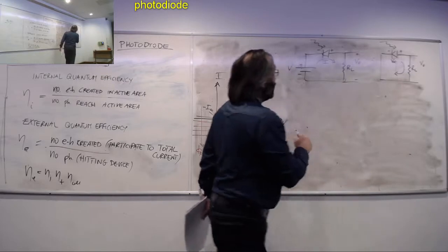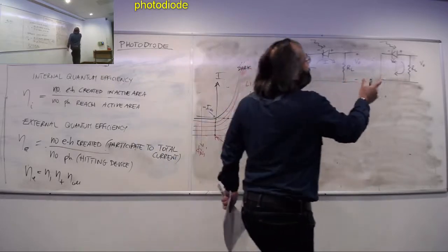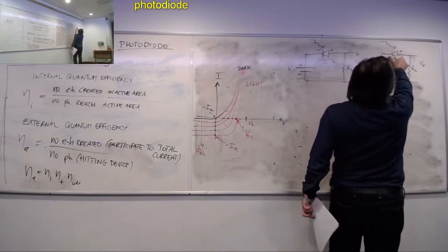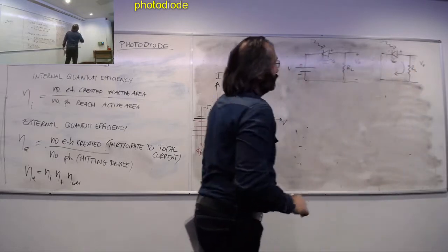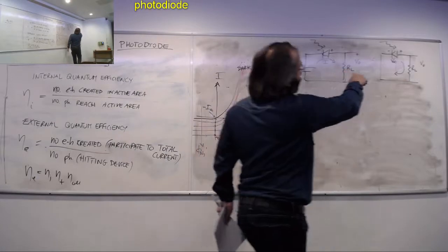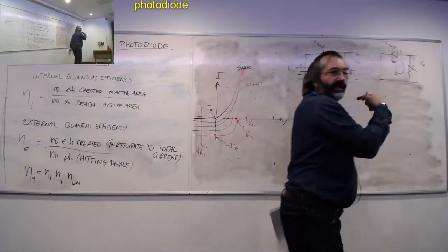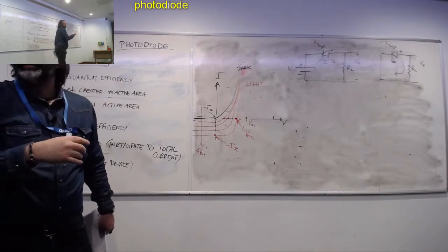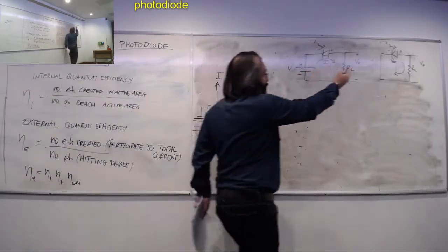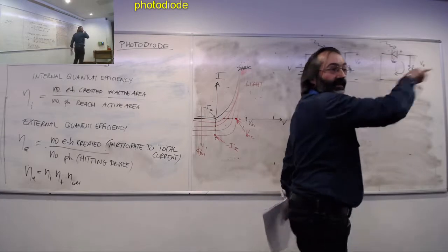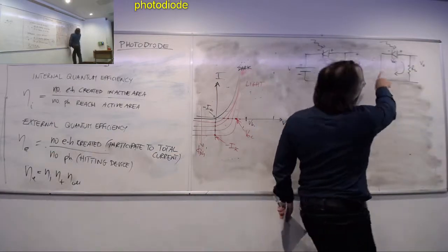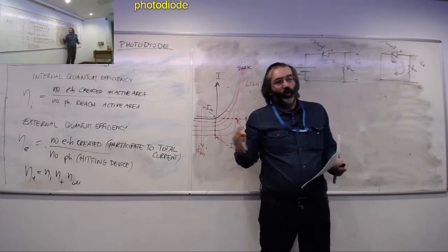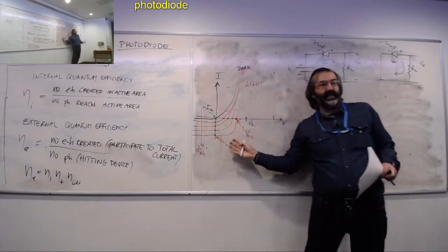So in this case, there will be a certain voltage across the device, positive now, as I indicated here, with some current. But the current, remember, as we said previously in our initial analysis, is because of the light and goes from N to P, as I indicated here. So the current, on this plot, would be the negative part.